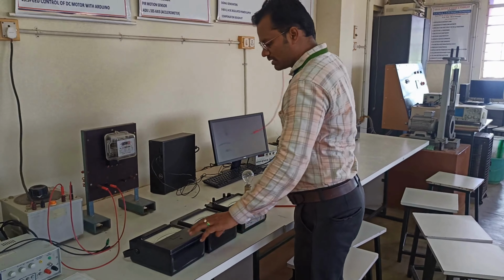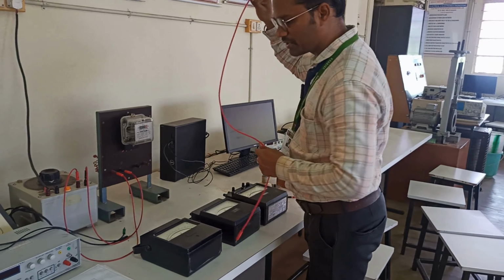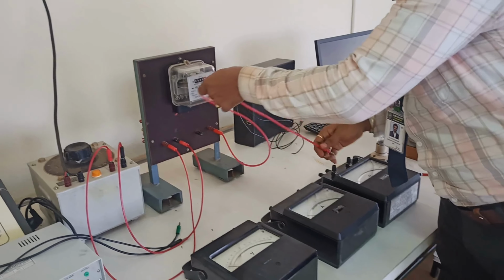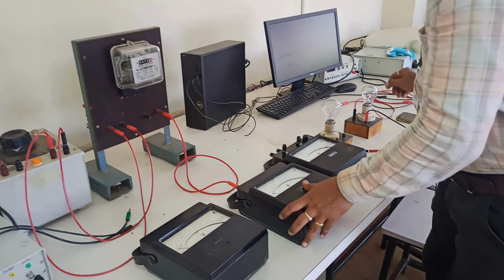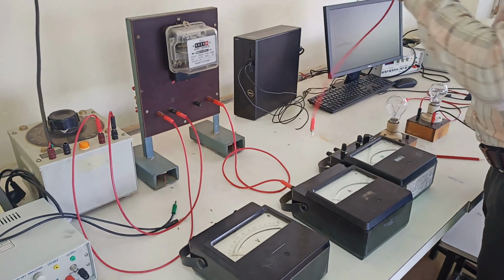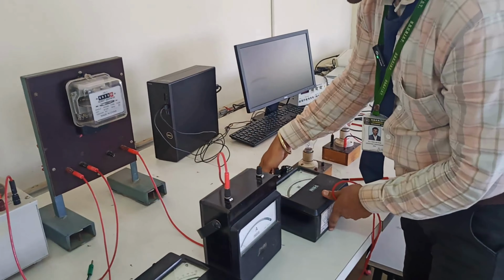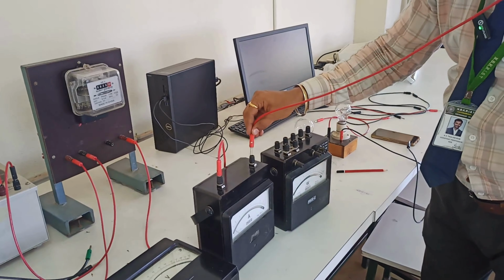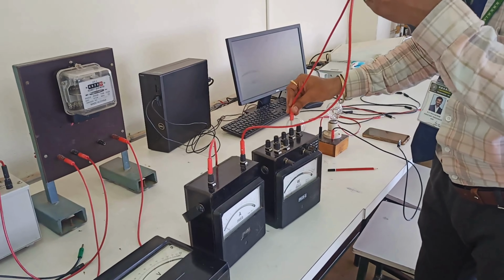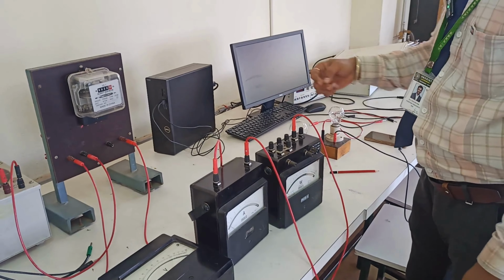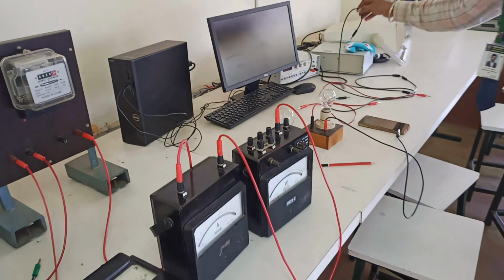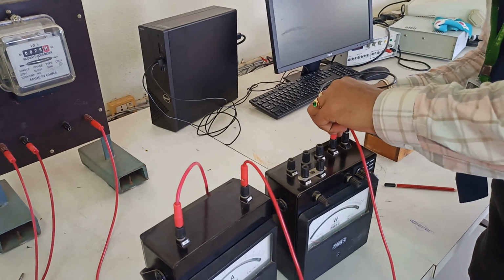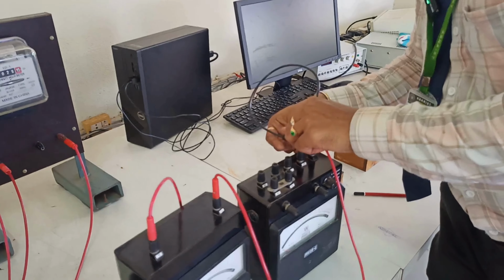First, the voltmeter we will give later. First we'll try to give the ammeter connection. So from the phase connect to the ammeter, and the output of the ammeter. You can see here, I will make it in vertical position, then you can understand better. So this is the input of the ammeter, and the output of the ammeter we have to connect at M, and M and C have to be short circuited with a small wire. Okay. So this is nothing but the short circuit wire. We are going to short circuit M as well as C. So now M and C is short circuited.